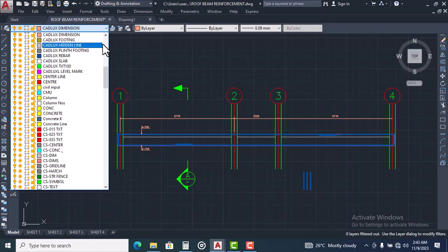Although there are major differences between links and steel rods, steel rods are provided in the beam to resist the shear force. You understand? Links or ties are for columns. So these are the two differences. I would say steel rods are mainly for beams, to resist the shear force that comes on the beam, like the load on the beam. While links or ties, we call them links or ties, they are provided in columns just to hold the main reinforcement vertically. So this is just the difference between steel rods and links.